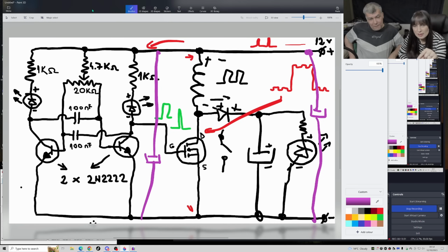But you said this capacitor is going to give you the smooth signal. Exactly. So you can put it anywhere. I can put it here or here, it will be the same thing because it's between plus and minus, right? Yeah, but if you want a smooth signal, you want it from the beginning. So you're going to put it there. The beginning, this is a wire, a 0 ohms wire.